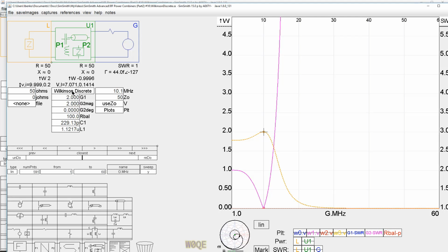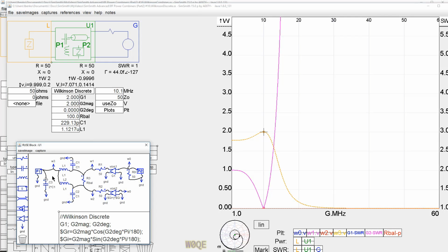All right, here's an example of the same circuit being replaced with capacitors and inductors, where this C1, L1, and half of C2 is a 3-element pi network that gives me a 90-degree phase shift at 10 megahertz. Now, if we look at our circuit here, we see it's different than before. This circuit has no other frequencies where it actually acts as a power combiner. It only works at the proper frequency. That might be a plus. It's got a narrower SWR bandwidth than the other circuit had.